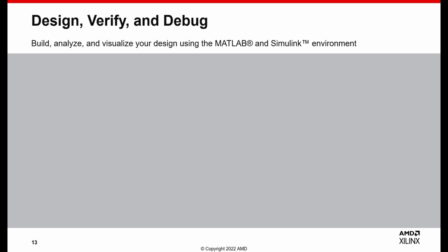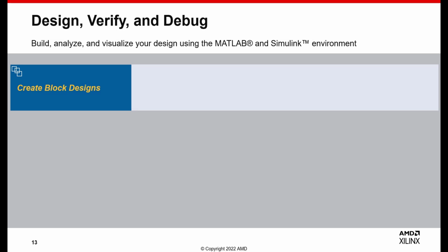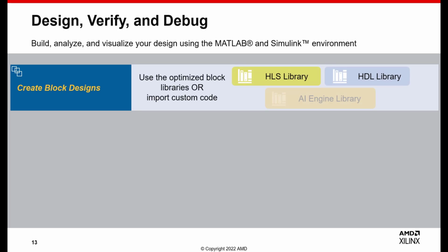Using the MATLAB and Simulink environment, you can design, analyze, and visualize your design. Here is how you can do it. Create block designs by using the optimized AI Engine, HLS, and HDL blocks directly from the Simulink library browser, or by importing custom AI Engine, HLS, and HDL code as blocks if required.